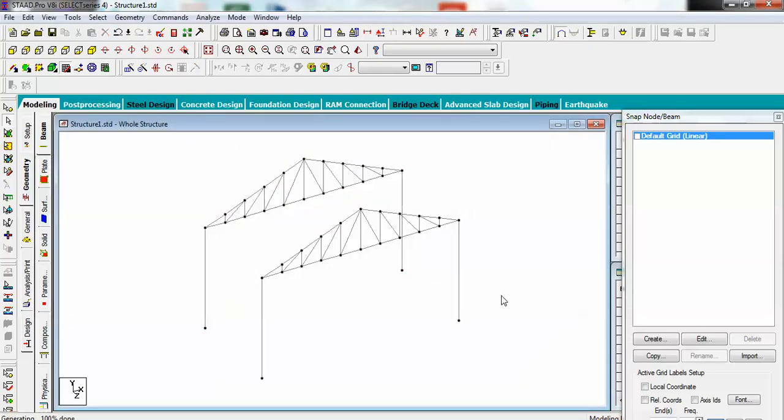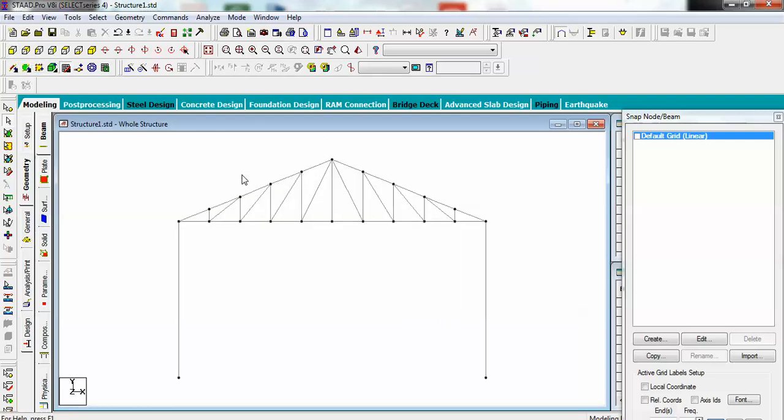So now you have these two instances. Now I want to link these nodes, so let's just orient it from Z direction, and then just select these nodes like this. Sorry, I have to go to node cursor and select them like this, and select them also.